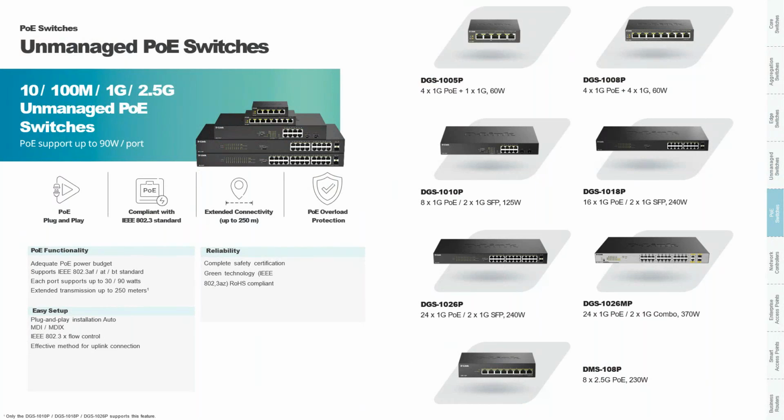These are the newer versions, aren't they? So that's been added to these newer ones. Traditionally PoE, the distance is 100. Yeah. And if I'm not mistaken, you also have the ability to choose two additional. So the actual physical dip switch allows you to turn on and off things like flow control, port isolation to isolate each of the ports, and also what we mentioned earlier, PD alive, to enable the port to power off and on the PoE port if it senses inactivity on the port itself.